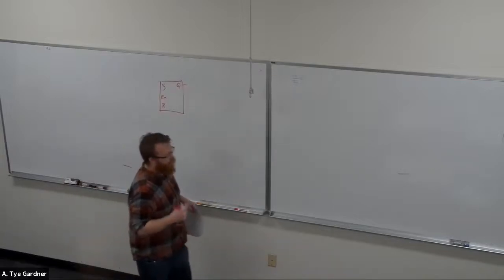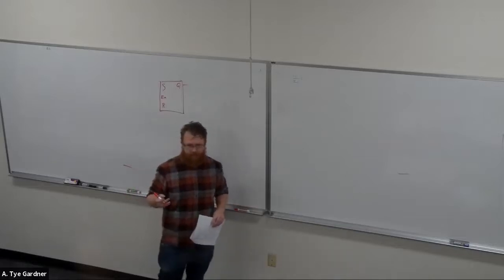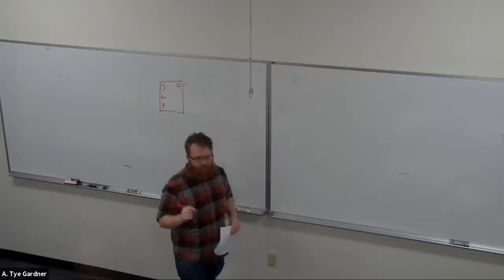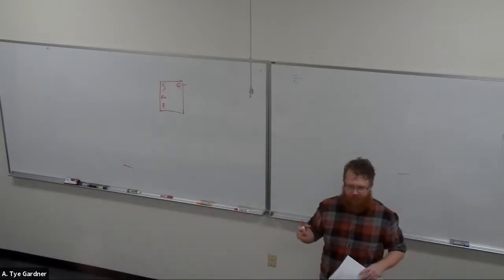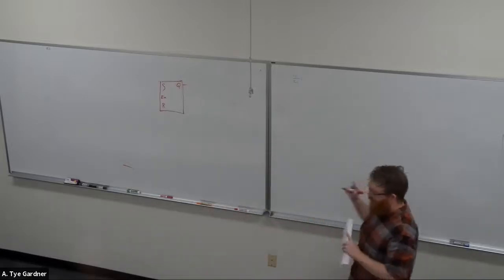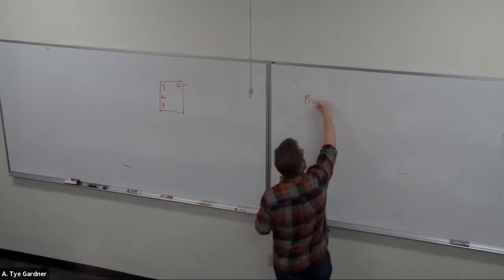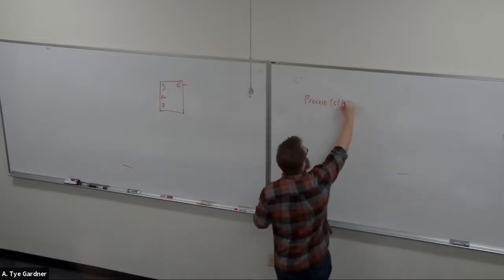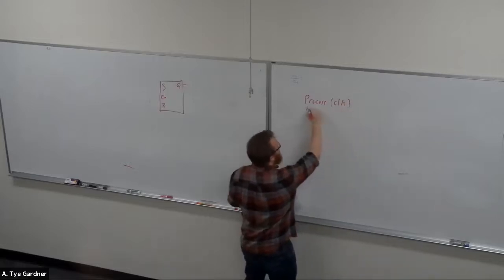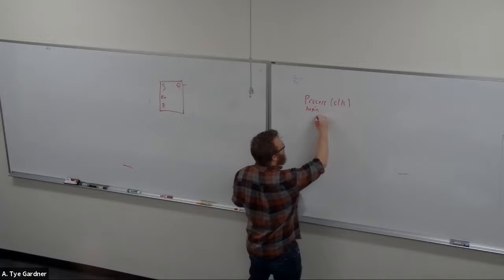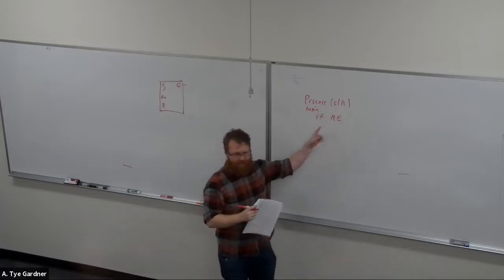So we've started talking about processes, right? And we started designing some processes, or at least you should in chapter 12, which is how do we design flip-flops, things with memory. So if I were to write something like process on a clock, this is a sensitivity list. Begin. If rising edge, right? I need this, otherwise it's not going to work.